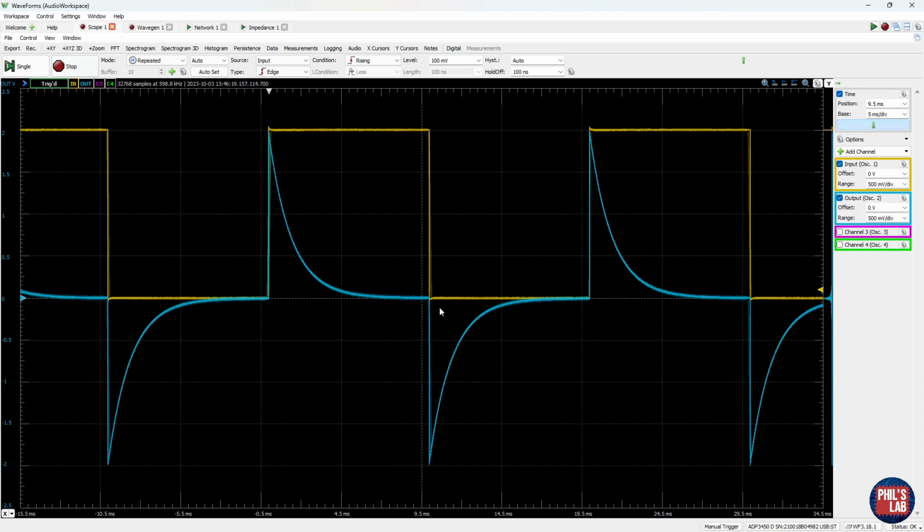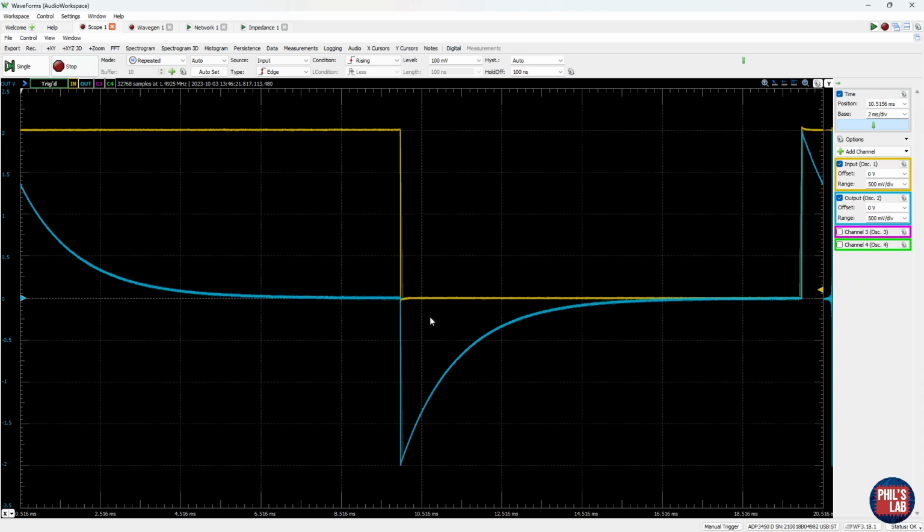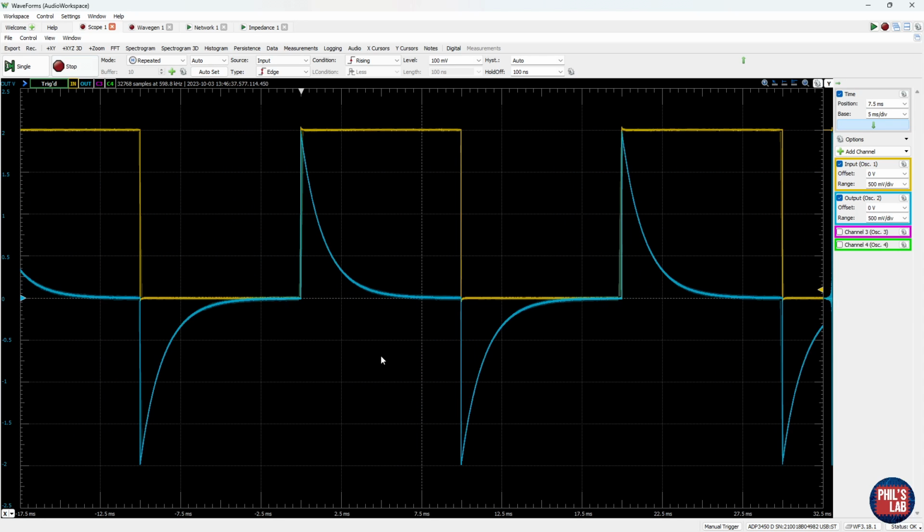Similarly, on the falling edge of the input signal, this yellow trace, we get a very similar response, except it's mirrored. We get a negative output voltage at the output of our RC high-pass filter. So falling edge, and then decaying exponential back to 0 volts, our DC signal. Remember, our time constant was about 5 milliseconds, so let's see if this holds true. I'll add just a quick measurement, and this is fairly rough. Remember, this is about 10 to 90%. If we look at what 5 milliseconds is about, which was our 2.2 times RC, we can see this encapsulates most of this decay time of our falling output at the output of the RC high-pass filter. So this is why we have this RC time constant.